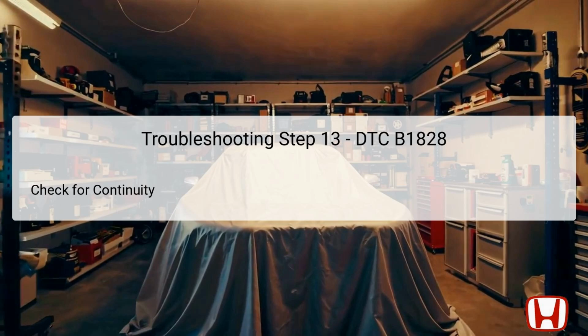If continuity is present, this indicates that the wiring is intact and functioning as it should, allowing continued troubleshooting of other components. Conversely, lack of continuity may suggest damaged wires or connectors that would need repair or replacement. This diagnostic step is fundamental in troubleshooting potential electrical issues among interconnected vehicle systems.